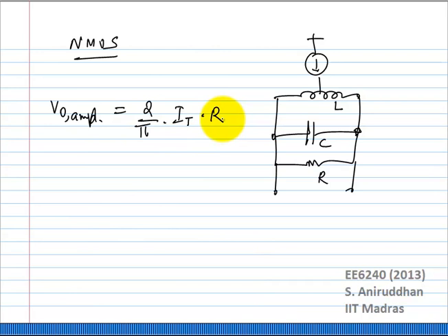And that really is the right way to compare two circuits. Because obviously if I can double the inductance for the same Q, for the same set of losses, I will get double the resistance probably. So you can't have different values of inductances and try to compare it.